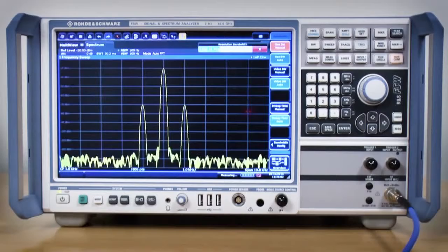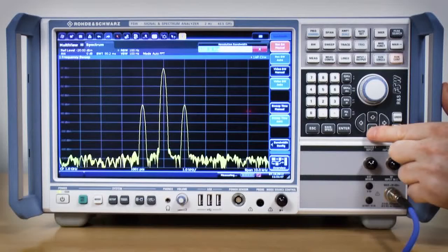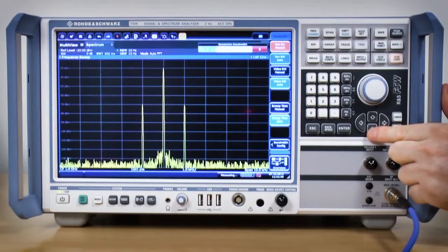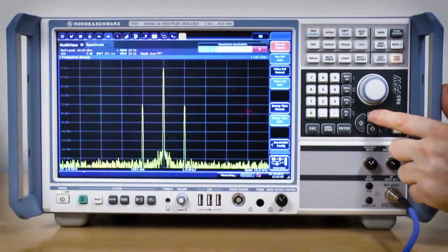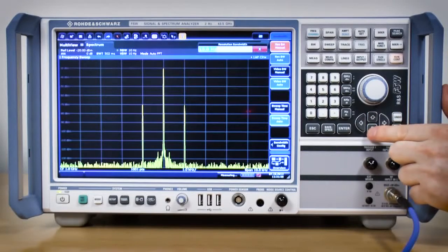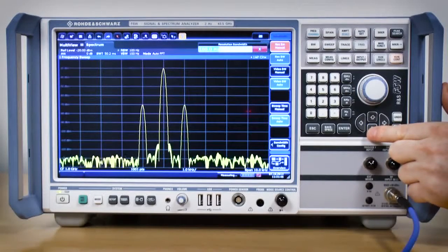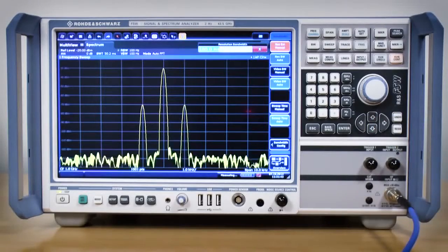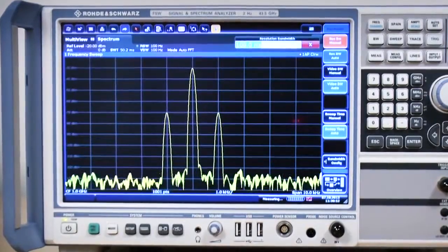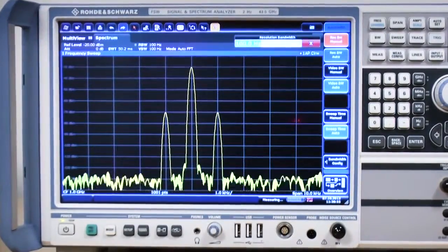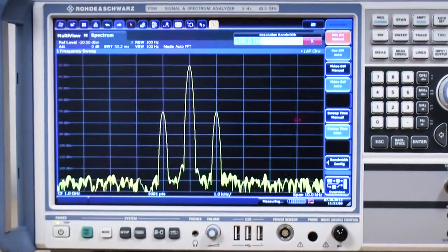This is the same as the reception bandwidth of a radio. The smaller the resolution bandwidth is, then the higher the resolution of the scan, the more detail there is. The downside to a narrow resolution bandwidth is that the scan takes longer to perform. As a result, a spectrum analyzer links narrower resolution bandwidths to the smaller overall scan widths, otherwise they just take too long. The noise level also falls for lower resolution bandwidths because the noise is proportional to the bandwidth. This means it's easier to see lower level signals because they're not masked out by the noise.